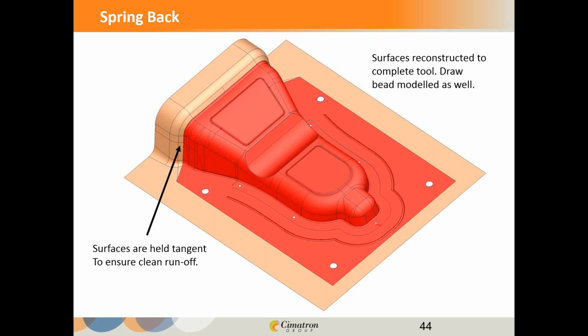With that, we'd be ready now to go back and finish up the die side by blending in the areas from the binder that we deformed to the tool steel that was originally designed. At this time, I might go ahead and drop in the draw bead as well if I had chosen to use that. Actually model it up now as 3D. When I showed you the draw bead earlier in running the blank function, we asked for the center line and we asked for a pressure. So really it's kind of a predictive tool for a draw bead.